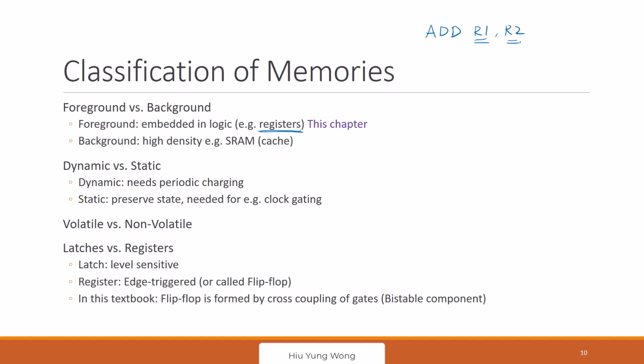If you miss something, you need to copy from SRAM. You know SRAM is very fast already. They are on chip, but still not as fast as the register, right? So the register is the fastest. So when you do pipeline design, which we don't talk about in this class, all this sequential logic we're talking about uses registers. They are not SRAM. Okay, that is the first thing.